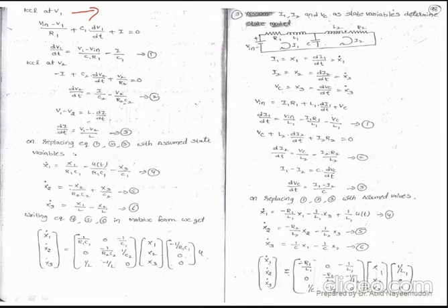So if you observe, your circuit looks like this. This is VR, this is your C, and this is your L. This is V1, and the other end is connected to Vin. Now, if you apply KCL at this particular node, I can write (V1 minus Vin) by R1, that is V by R, plus C1 into dV/dt plus I is equal to 0.